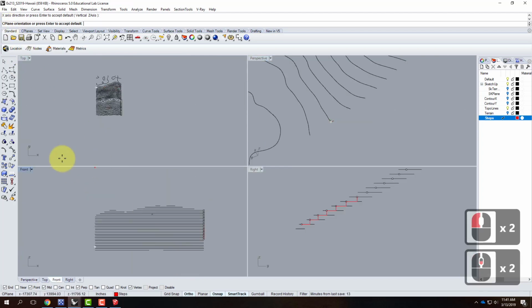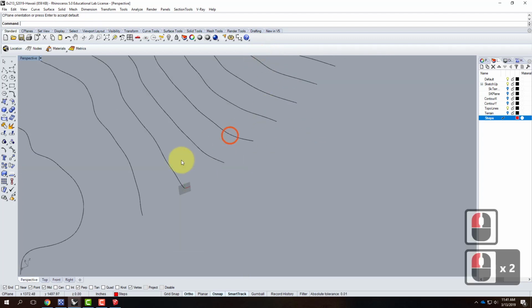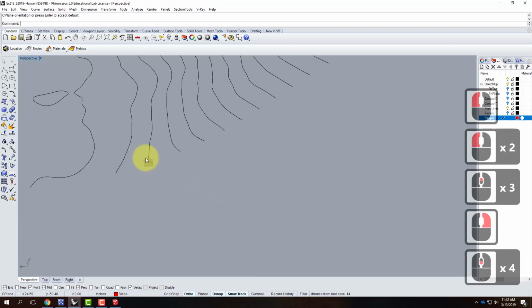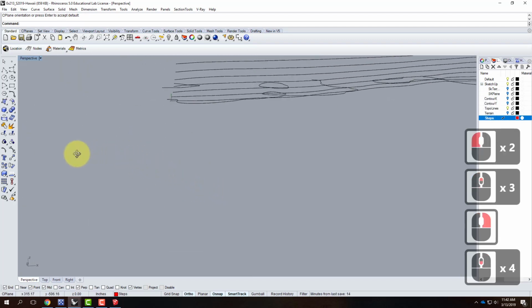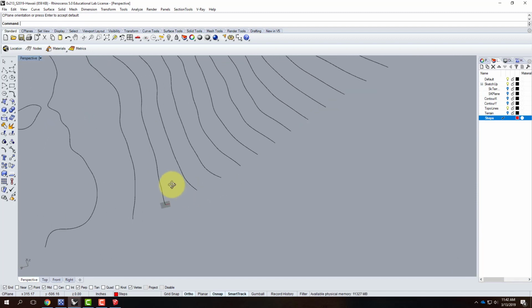So I'll go over here, and I'll go to vertical in the front view or in the right side view. So again, I'm not snapping to anything. I'm just using my axes and my ortho to make sure that I'm in line. And once I'm done, my little grid will change to be on that point. And you can kind of orbit around to confirm that, yes, it looks like it's in the correct orientation.